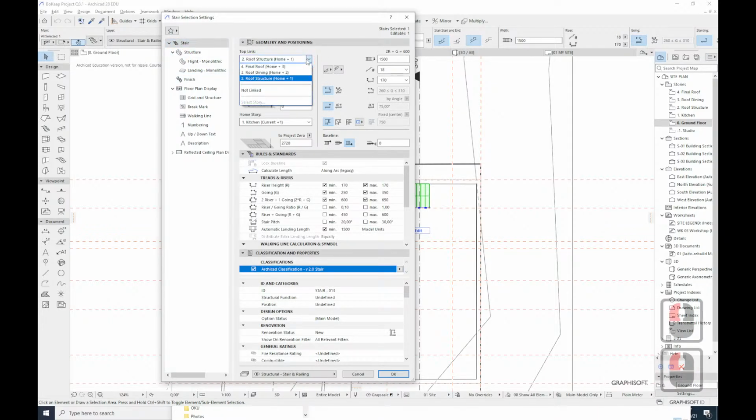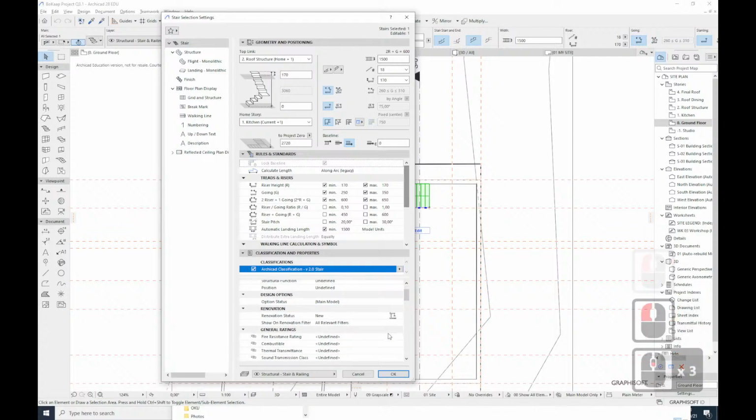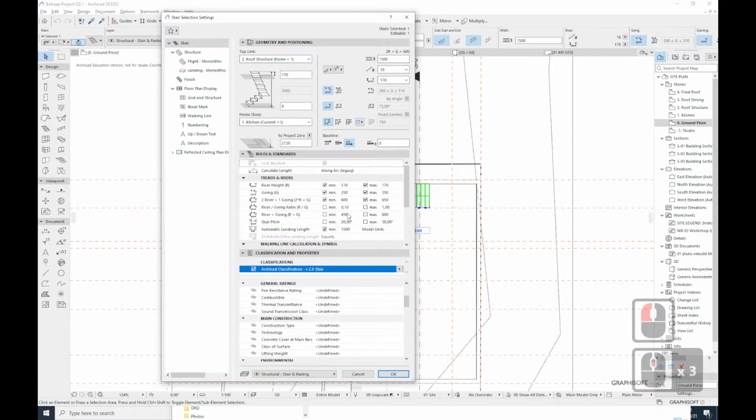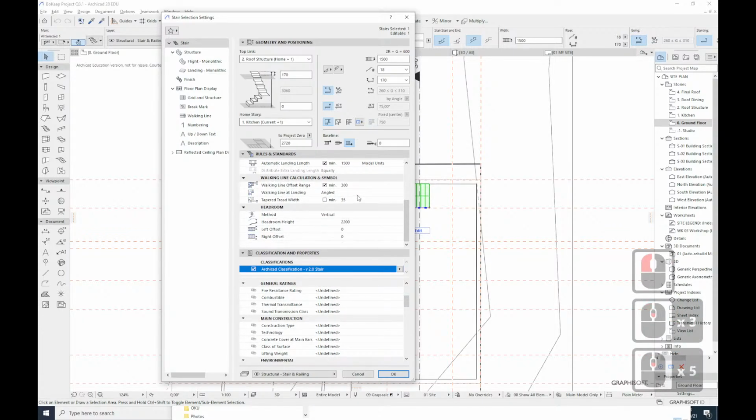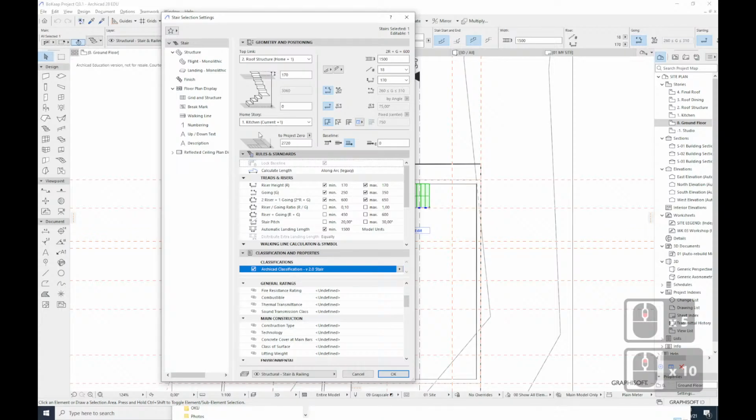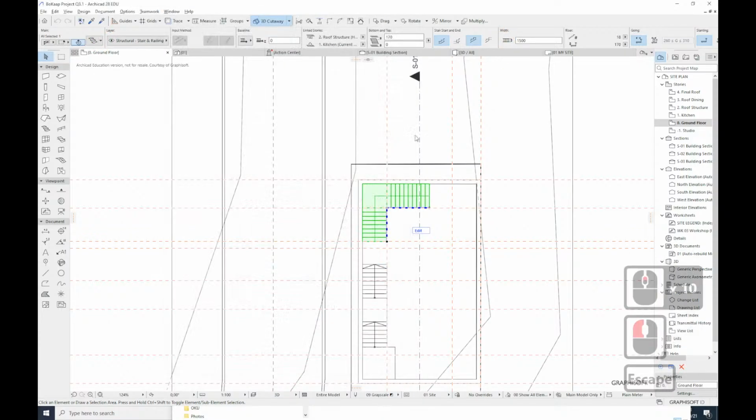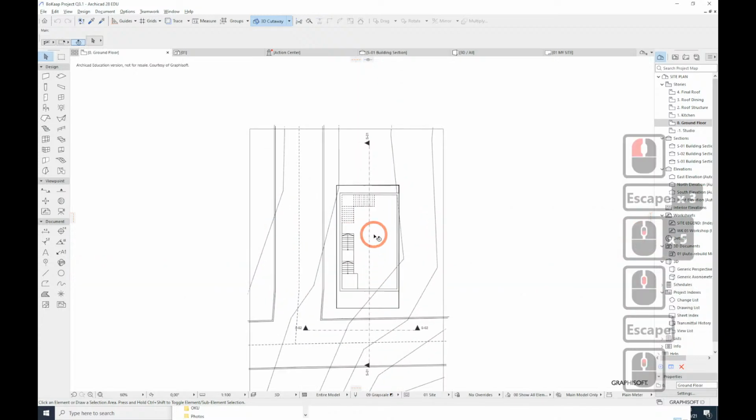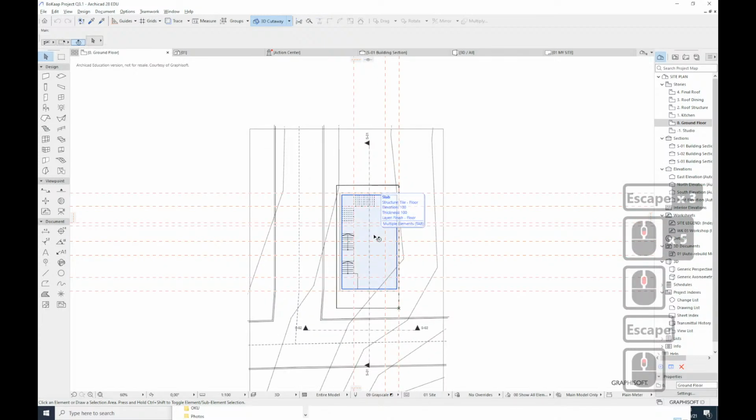So if you don't link it to roof and you say not linked and you select a story, it will only show on that story. Certain elements do that in ArchiCAD, so just be careful. This will tell you what levels it can be visible or not visible. Just bear that in mind. Certain families do the same thing. They're only visible on a certain level, not all.